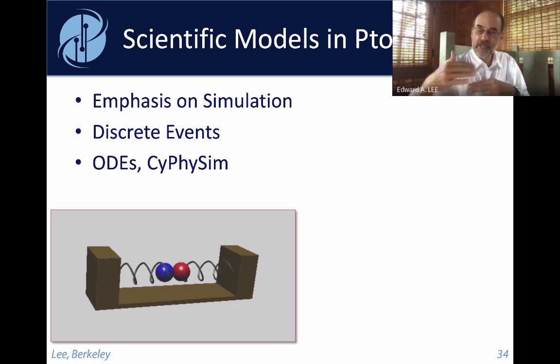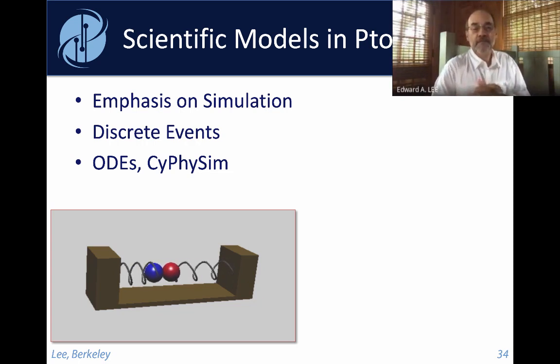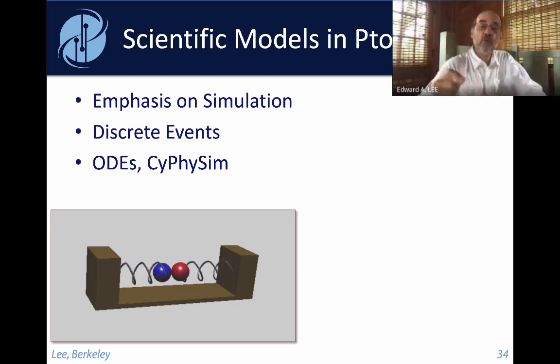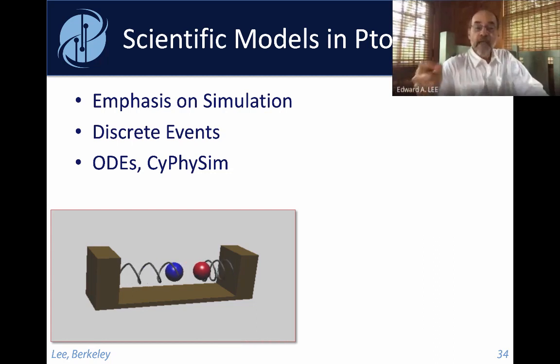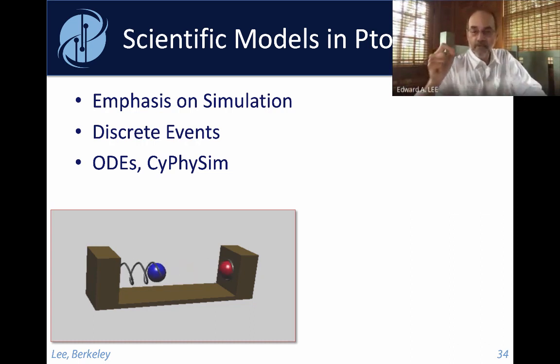And so they designed a feedback system that would inject a force that would countervail the motion of the finger. And then they discovered, Mark Lemkin in his PhD thesis, discovered that he could use the feedback control signal itself as a measurement of the acceleration. It was a beautiful design.